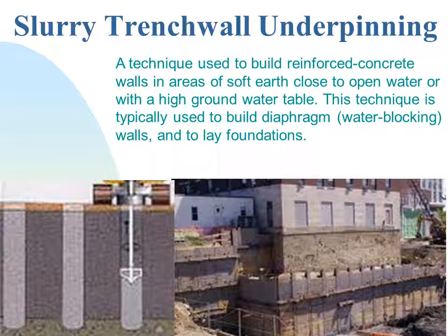Then comes option number 6, which is the slurry trench wall underpinning. This is valid if you have a group of piles or a group of footings that failed, or maybe one side of the structure has suffered significant loss of bearing capacity under it, or suffered significant swell or differential settlements. In such a case, you will need to increase the bearing capacity of the soil itself by encapsulating it with diaphragm walls.